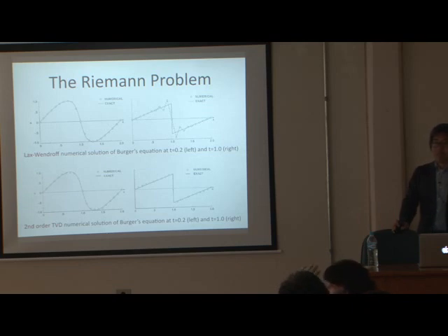But of course, in SPH this artificial viscosity is a problem: how much viscosity do we need to put in there? This is done by hand. If you put in too strong a viscosity, we have strong dissipation, and the shock structure is smeared out so much. You need to make a lot of tests. This is fine tuning of the simulation. But after several tests, you know the numbers. You have the right numbers, and it works.